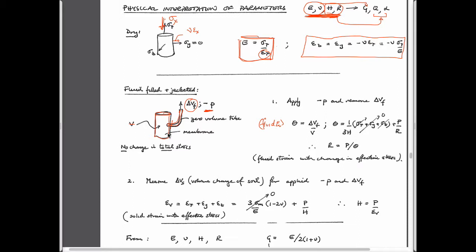Well, we have a sample. The external stresses are atmospheric. When we suck on it from the inside, the external stresses don't change. There's still atmospheric pressure acting on the outside. And so the changes in these, as we talked about when we discussed the other constitutive matrices, this is the change in stress and the change in strain that results from that change in stress. So likewise, the changes in stresses are 0.